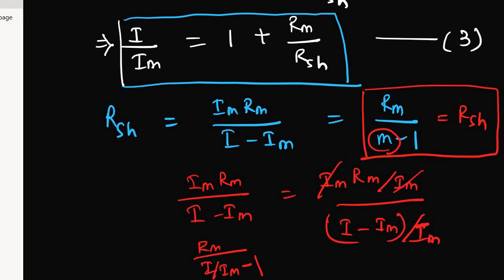And normally the shunt is made up of manganin or constantan. Those are alloys, chosen depending upon the nature of the devices where we are putting the shunt. And also we should consider the temperature coefficient as well as the temperature endurance of the material, so that we will have a suitable range of temperature endurance in the shunt circuit. So this is it for the shunt ammeter.